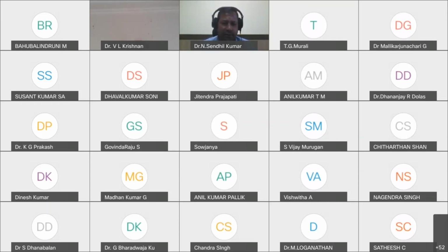The second problem is if the panel is not inclined or not installed properly, it will show in our efficiency. So we can easily predict why the efficiency is very low. We have to analyze that. If you analyze the PV panel, we will come to know whether it is properly installed or not, whether any dust accumulation is there or not, whether cells are properly placed or not. Sometimes cell damage also leads to poor performance.